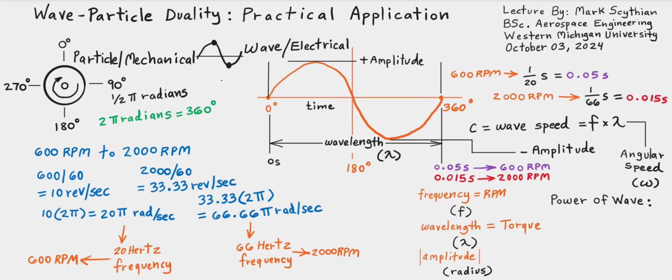So assume that you needed information about the RPM, the torque, the total brake horsepower, the mechanical wattage, etc. So essentially you were able to convert an alternator into a brake dynamometer for, let's say, engine metrics testing across different RPMs.